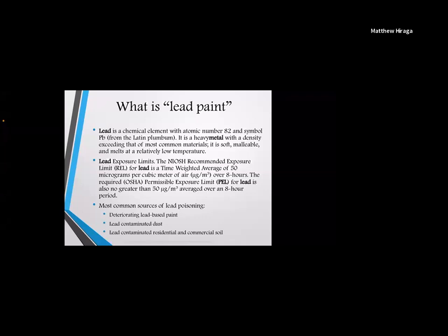Now, OSHA's permissible exposure limit, which is more commonly used, especially in construction, is also 50 micrograms per cubic meter of air. So they match, and they said, this is the number that a worker could legally breathe 8 hours a day with no respiratory protection, 40 hours a week, 2,050 hours a year, depending on if it's leap year, and you should be okay.